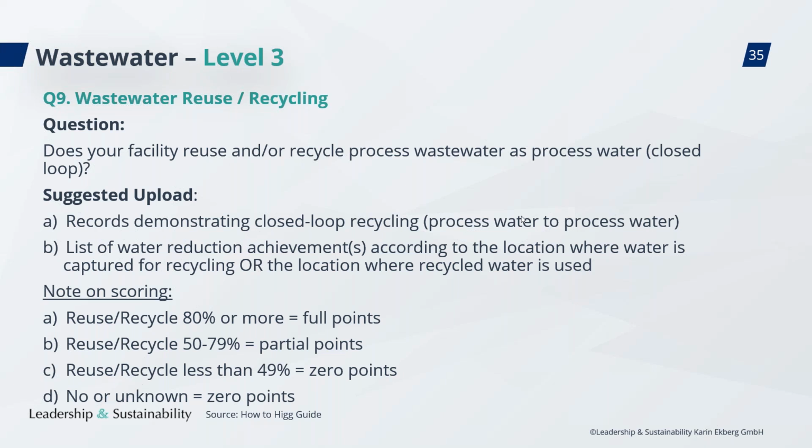It may be that they do that via analytics, that they tell if you have concentrations of certain chemicals in the sludge, then it is hazardous. But it may also be that they say, for example, that all sludge from all wastewater treatment plants is automatically hazardous. So you need to go and check your local regulation.